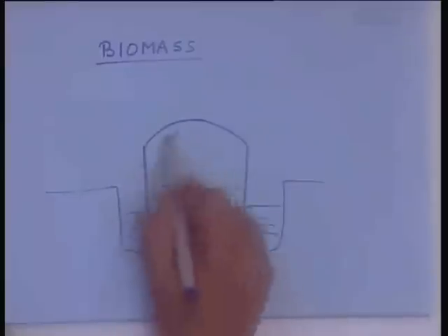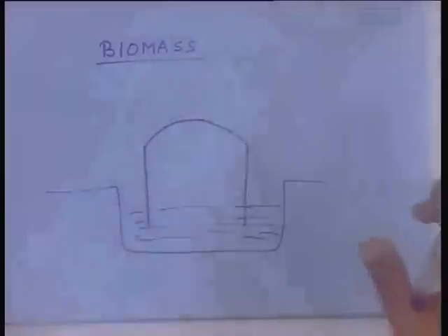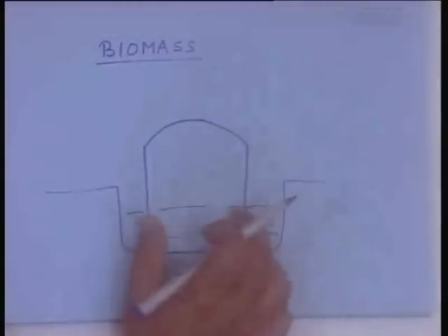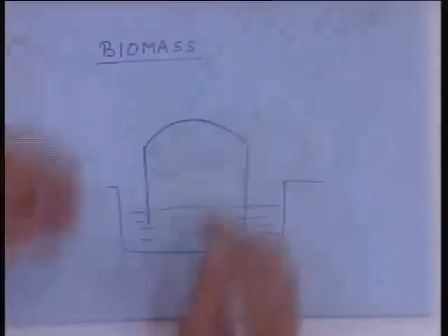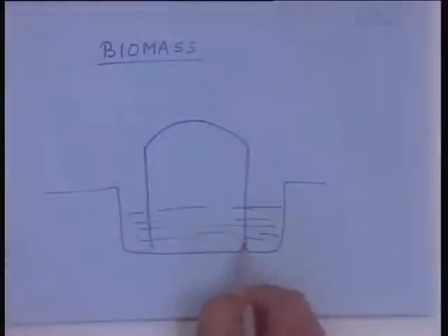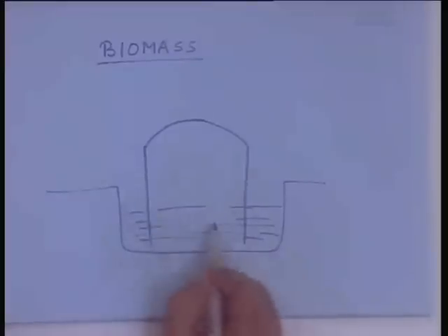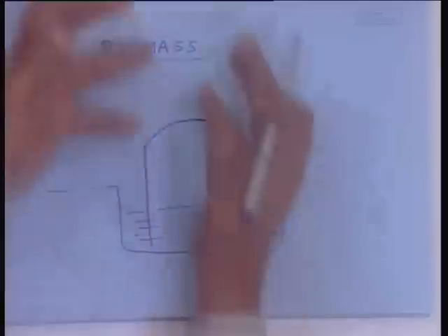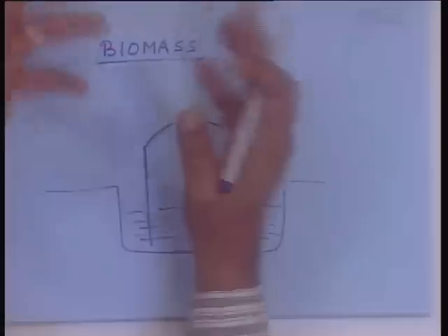and you have this iron material that is upside down, and normally it would sink to the bottom like this, and as the cow dung that is normally mixed with some bacteria, that means some bacteria has to be put into it, and as the methane is formed, what will happen? It will push the cylinder up. Okay, it will push the cylinder up. So, this cylinder slowly goes up, and because of the weight of the cylinder, the pressure inside is high. So, it will be somewhat pressurized natural gas, pressurized methane.